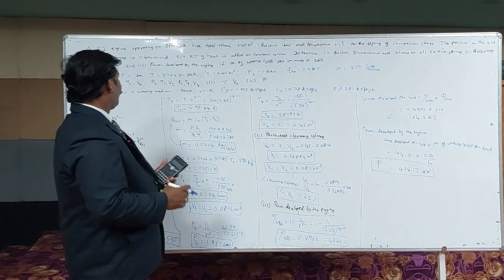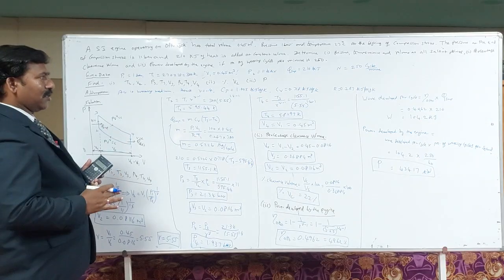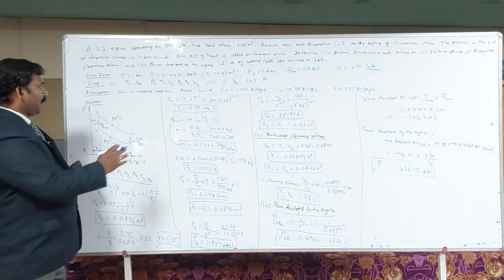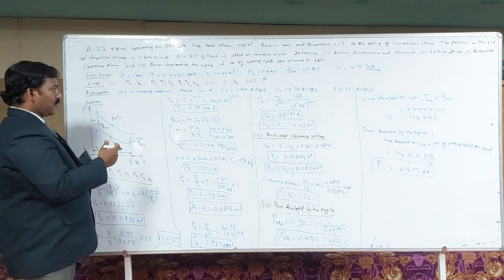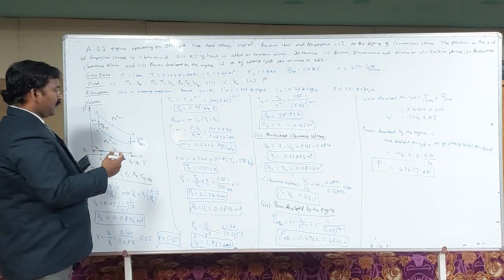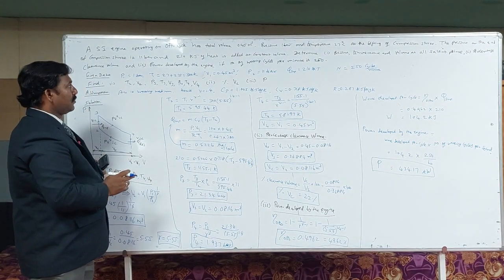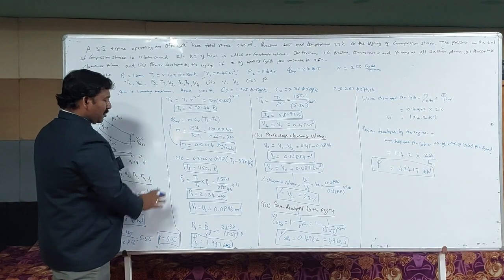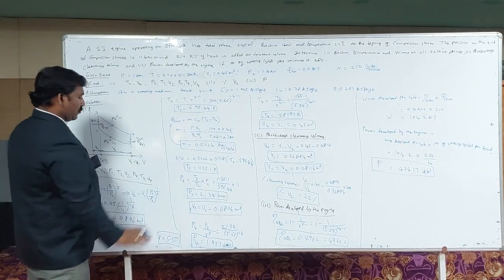So we have found out all the properties at salient points and percentage clearance volume and work developed. If you look at here, the temperature at T2 is more than T1. Since it is an isentropic compression process, it will be more than that. From process 2 to 3, there is a heat supply taking place of 210 kilojoule. Therefore, the temperature T3 is more than T2.